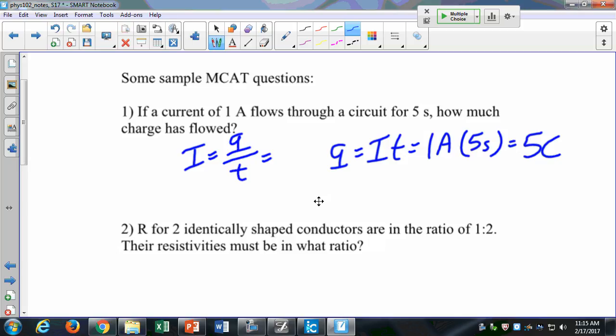Some of your circuits are 20 amps. Some of them might even be 30 amps. Look on your breaker box in your house, and often they'll have little numbers stamped into the ends of the breakers, and that'll tell you what maximum current you can have.